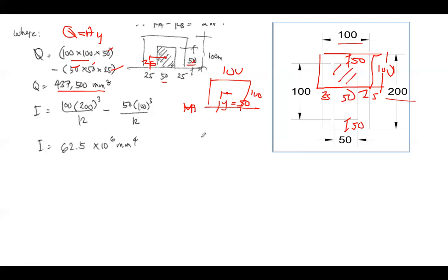Now, the moment of inertia, as simple as the moment of inertia of the big rectangle and then the small rectangle. The big rectangle is BD cube over 12, di ba? Ano yung B? Ito, 100. Ano yung D? Malaki pala ito. And D is 200, cube over 12. Yung small naman, itong sa gitna, 50 by 100.